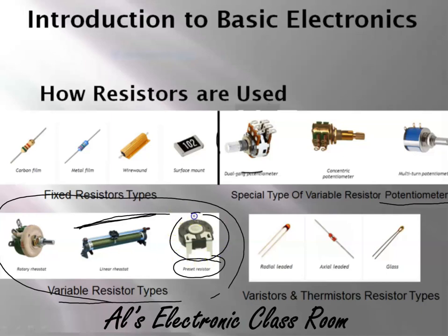Over here is like a screwdriver adjustment, and you turn this shaft, and that also adjusts the resistance. And here we have a shaft where we can turn the shaft and again change the resistance. In the next slide, they're coming. I don't remember exactly which order they're in. We're going to look at the differences between the potentiometer and the rheostat here.